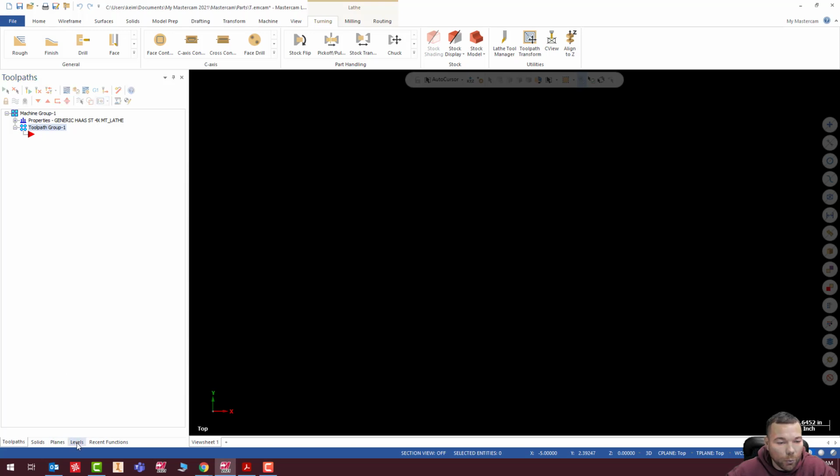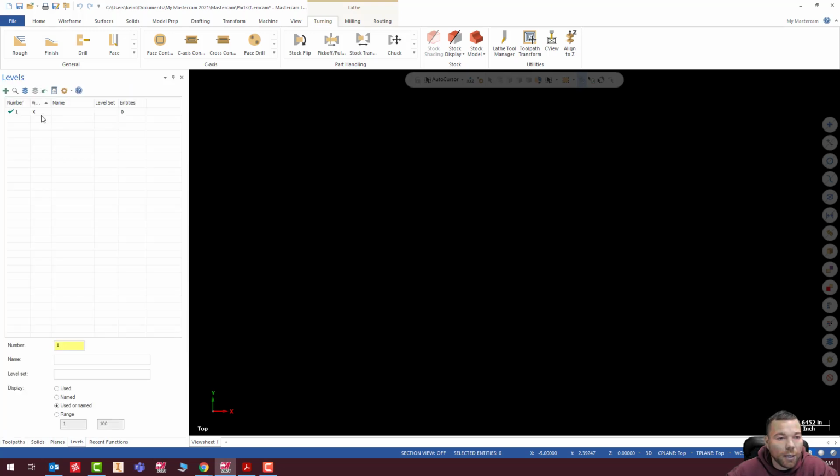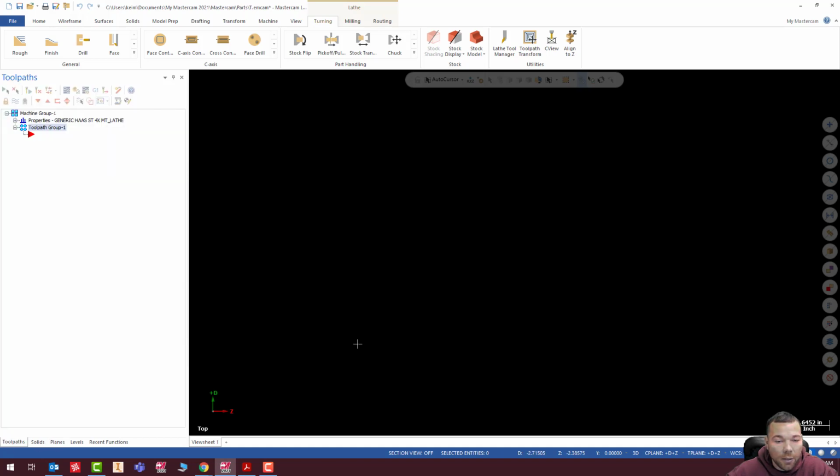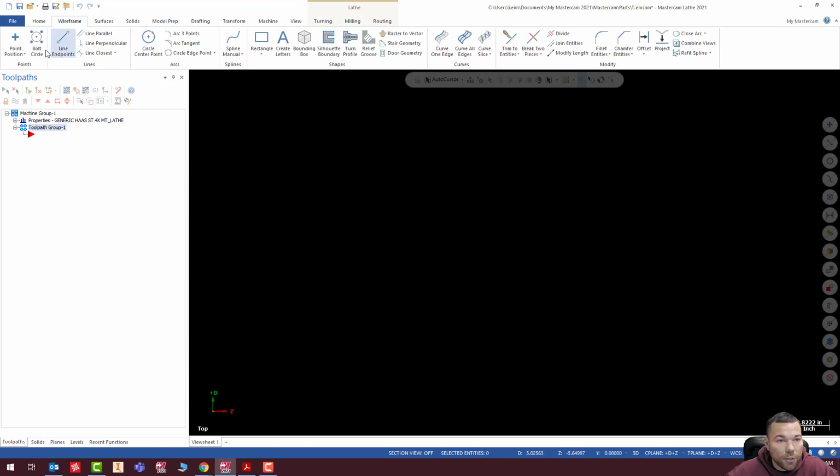Next thing I'm going to do is go to my planes, not levels. I'm going to go to my DZ plane and hit equals. Okay, so now I'm working on my DZ plane. All right, I am now set to start creating geometry.